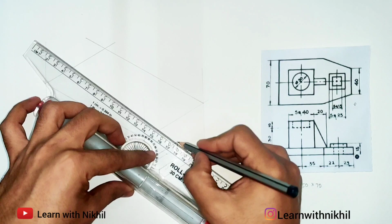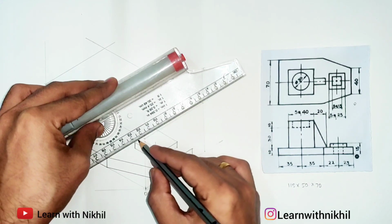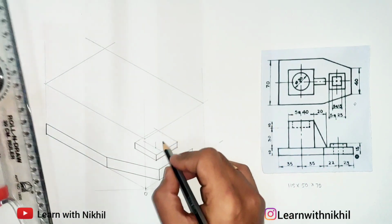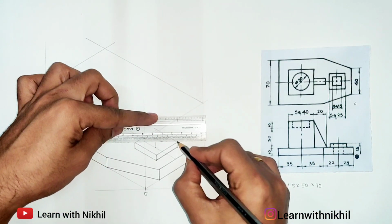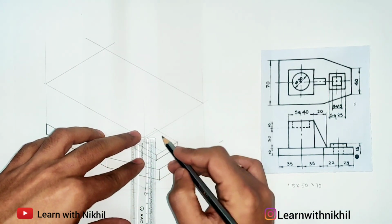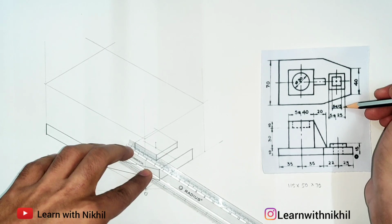Now drawing the inner square, the inner square side given is 15 millimeter. So same like this we can draw. So this I have completed the square. Now the inner square of 15 millimeter. So first I am plotting the center point. We have already got the center point. Now through that center point I'll draw a square of 15 millimeter.